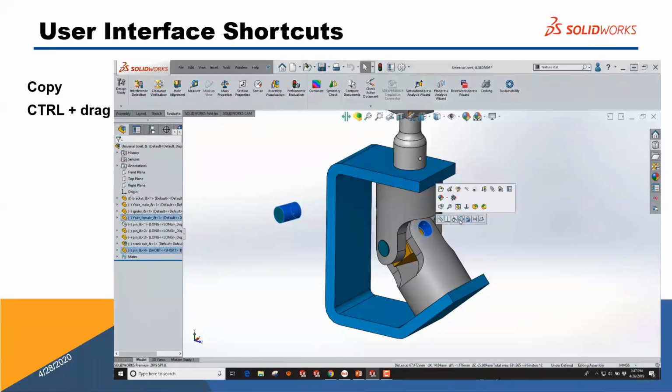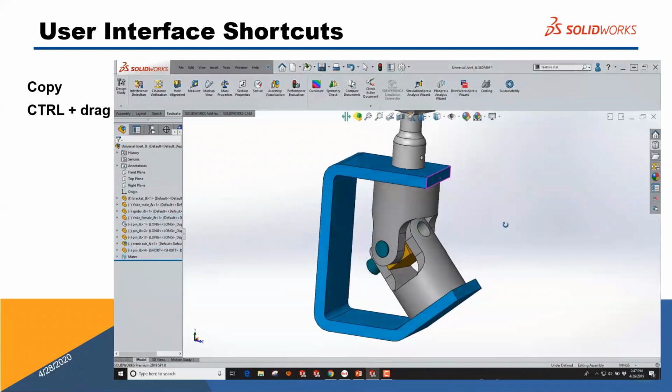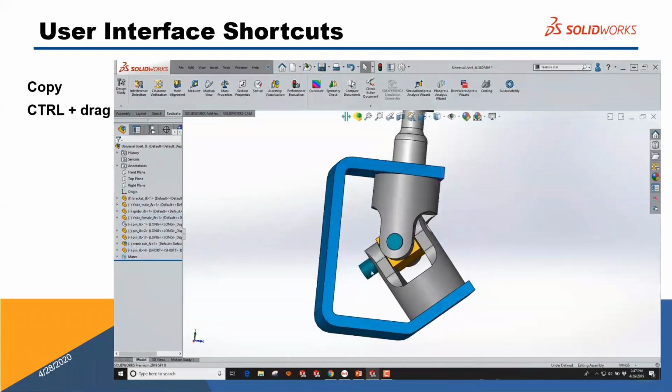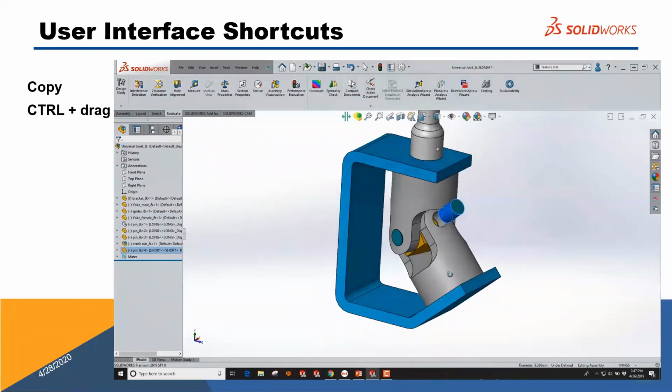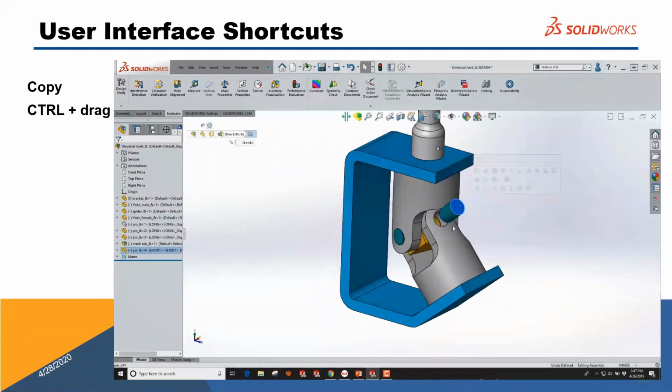Okay. Don't go back to your library to find out where that particular file is and get another one and drag it up here. If you have one in your model already, copy it. Okay. It shows up on the design tree the very same way as if you brought it in any other way. So it's a really, really huge time saver.